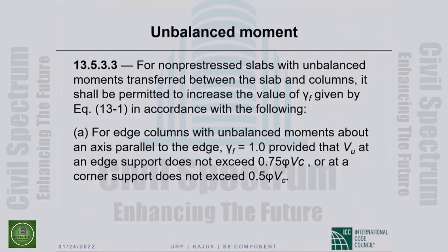So let us recap. The topic we are discussing is unbalanced moment transfer. I told you under gravity, it is pretty limited, except at the exterior support. Under lateral load, that is not the case. There is significant unbalanced moment transfer at every support.